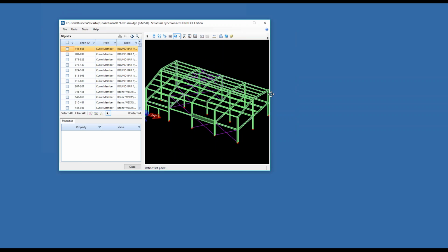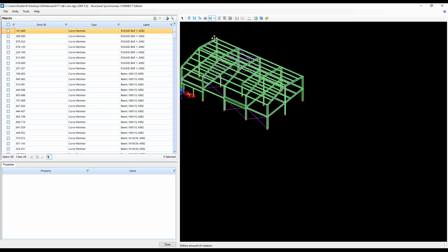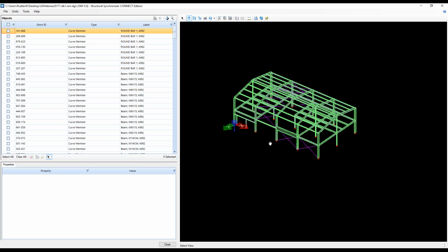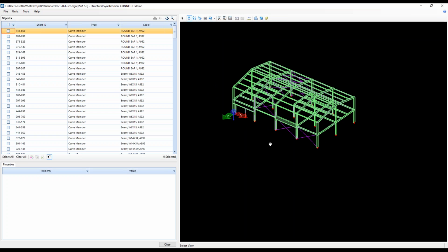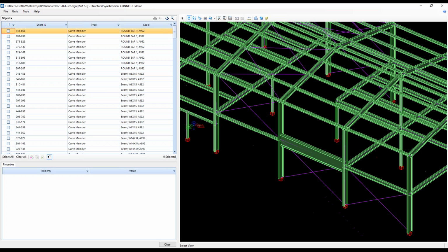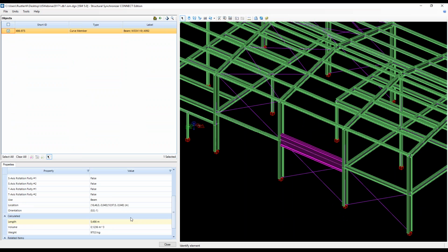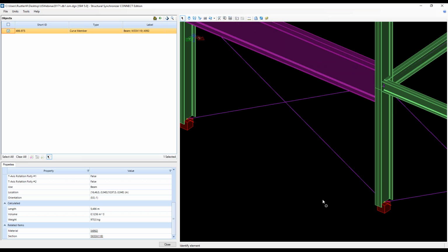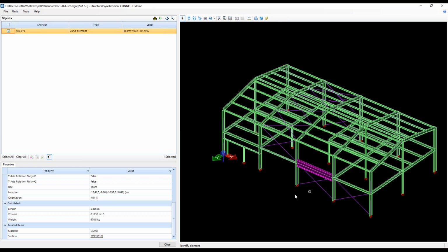I should have rotated the model, which has not been done yet, but that's possible to set up because the ISM only knows Z-axis up. Yeah, but you have all the information also here. I can click on it and read what is here, and there should be somewhere the cross-section designation, material designation, and ISM compatible software can actually read then also from this file.